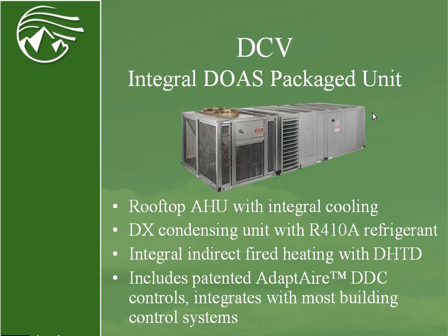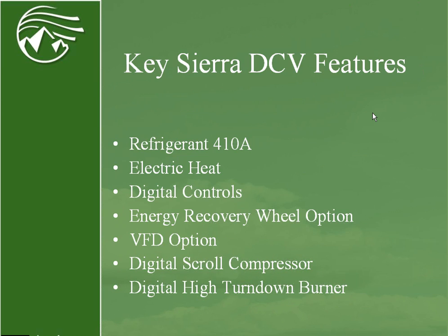And this DDC control system is phenomenal because it'll integrate with most front ends or other control systems. So your Modbus, your LON, your N2, LonWorks. So this will communicate to all your other systems as well. Some of the key features of this unit are the Puron refrigerant, the ability to add electric heat, the fully integrated digital controls, open protocol, incorporation of an energy recovery wheel, VFD options to modulate all the fans and the blowers.